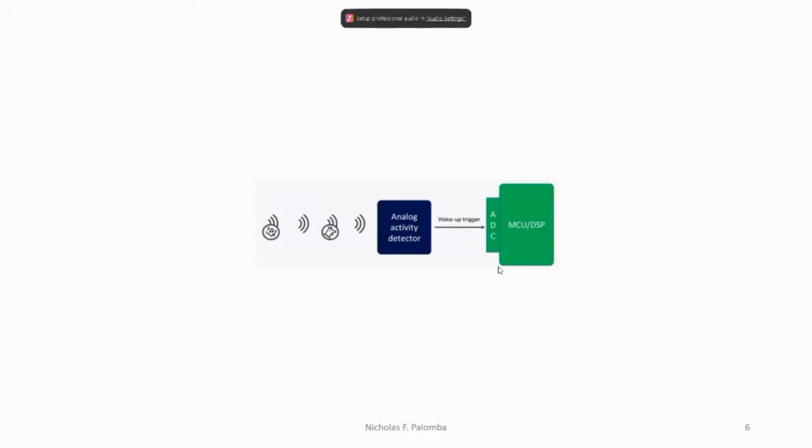So by providing a very low power always on mode for the system, this approach reduces energy consumption by keeping the digital system off for some of the time. Unfortunately, like I said, these simple analog circuits can't distinguish the type of event, and they typically detect too many false alarms that trigger the digital system wake up. So energy conservation improvements are again only incremental here.